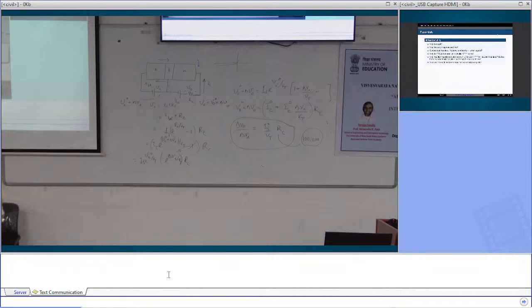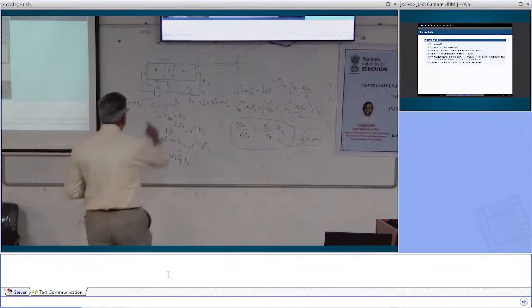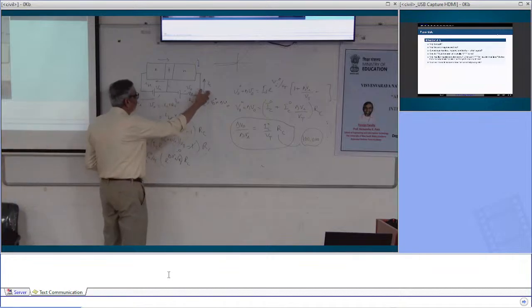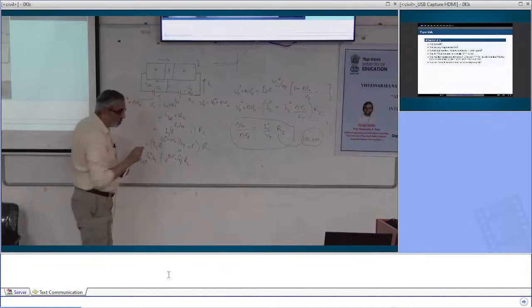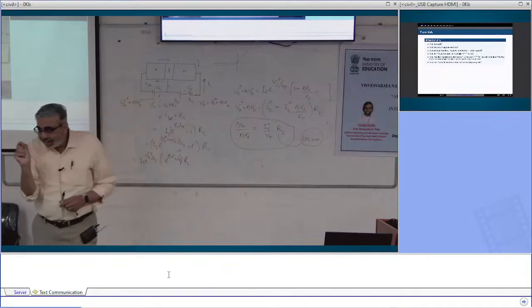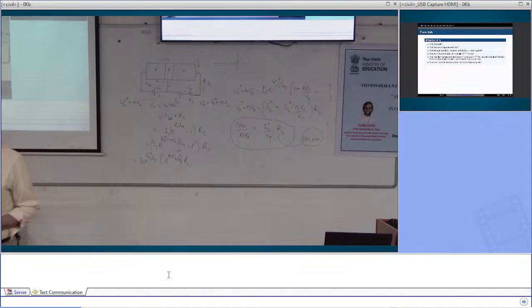The whole idea is that this side of the circuit does not matter what current is flowing, it will be exactly the same as that current. And that current can be changed by a large amount by a tiny change in the forward bias. And that large change, I am running it through the collector resistance RC to give me enormous voltage gains.